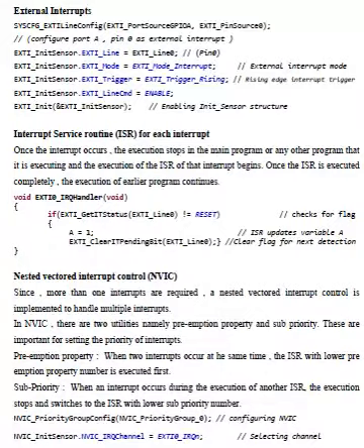So to start with, how do I use an external interrupt? What is an external interrupt? For example, if I have something like a Hall sensor signal or some digital signal which is given as an input, and based on it I have to follow a particular routine or a particular part of the code which has to be executed at the time of the interrupt. That is exactly what we mean by interrupts, and why they are different from just running a code sequentially